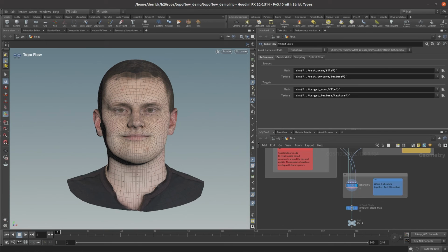For example, work with a lower resolution instead of a full 16K map, and limit the amount of values bled over UV boundaries, though this reduces the speed of the process a bit.